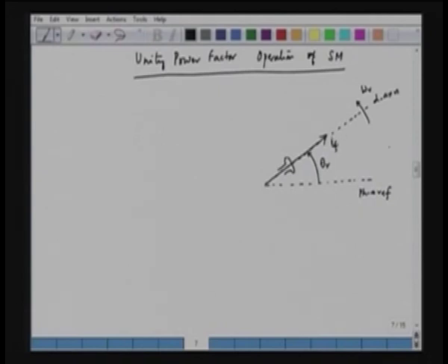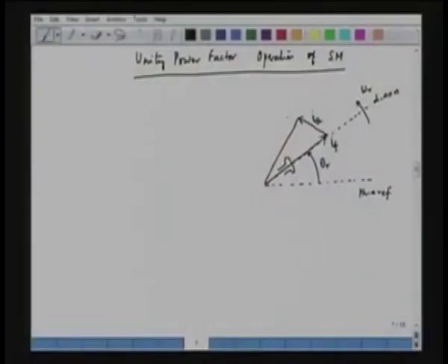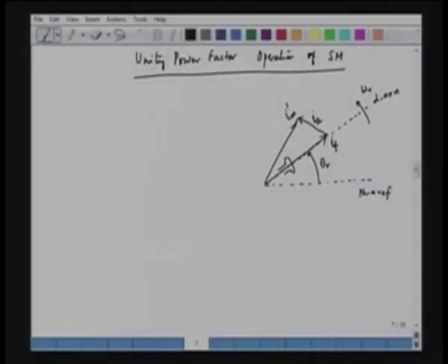We also have the armature current, which will be in this direction. We can call this IA. In the machine we have two excitations, the field excitation and the armature excitation, and the resultant of the field and the armature is the resultant current, which we call the magnetization current. So, this resultant MMF, or the magnetizing current, is Im prime, which is the resultant of the IF vector and the IA vector. Each one is a vector, because MMF is a vector, so we can represent each current as a vector. So, this Im is a vector along this direction.